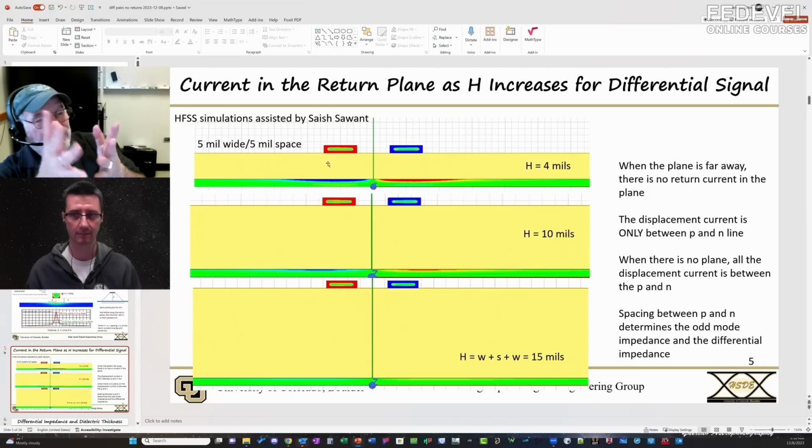Design it for 100 ohms. Darned if they didn't get a pretty good match to 100 ohms. So whether they're really far apart and uncoupled or really close together, and you optimize that line width for the coupling, you'll get the same 100 ohm impedance. The differential signal will never know the difference.